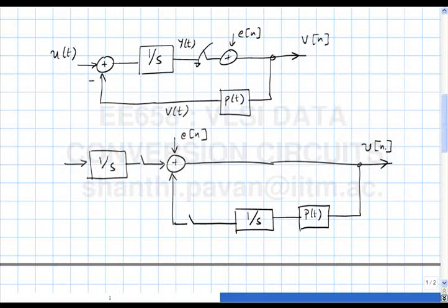Okay, you understand? This is a first order modulator. This is a remanipulated signal flow graph of the same first order modulator. So the transfer function from the quantization noise to the output still remains 1 minus Z inverse. Okay. So if the transfer function from E of n to V of n is 1 minus Z inverse, what is the transfer function from, let me call this signal auxiliary signal, R of n, I'm running out of alphabets here. Okay, no, X is for state variables, so I don't want to use X. Okay, alright.